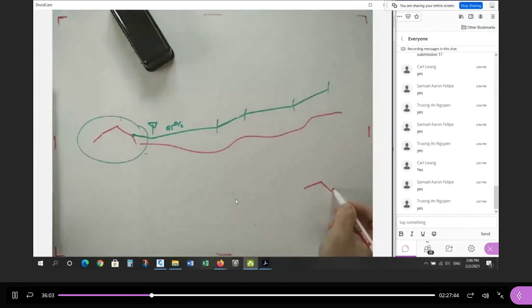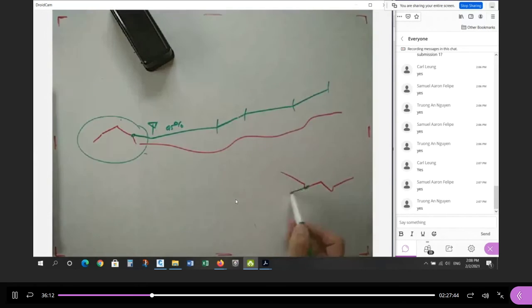So it would look like this existing urban road, and then in our design we're going to get rid of the boulevard. Our design would start at the edge of asphalt here, come down to a low point, and then come up through the subdivision. Sound familiar? But the topo doesn't show this cross section. The proposed road is not part of the existing topo. Everybody understand that?